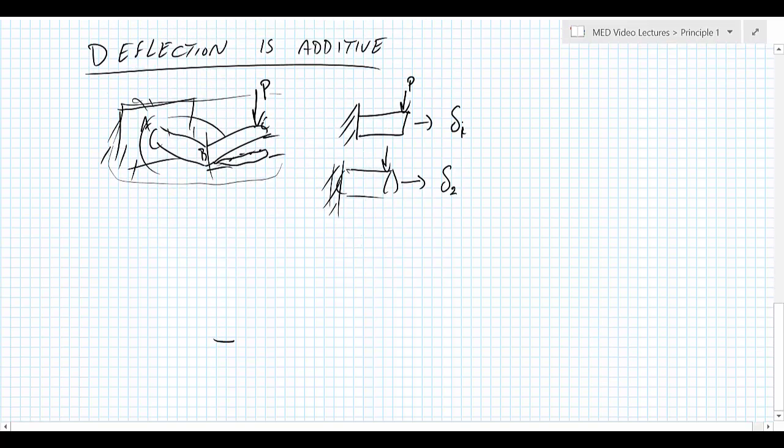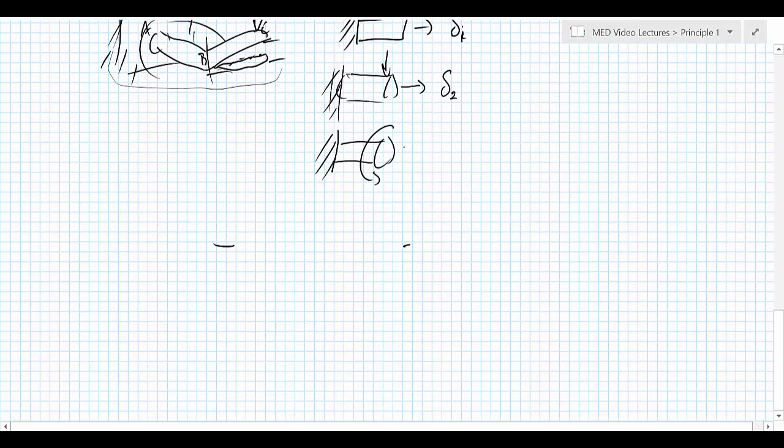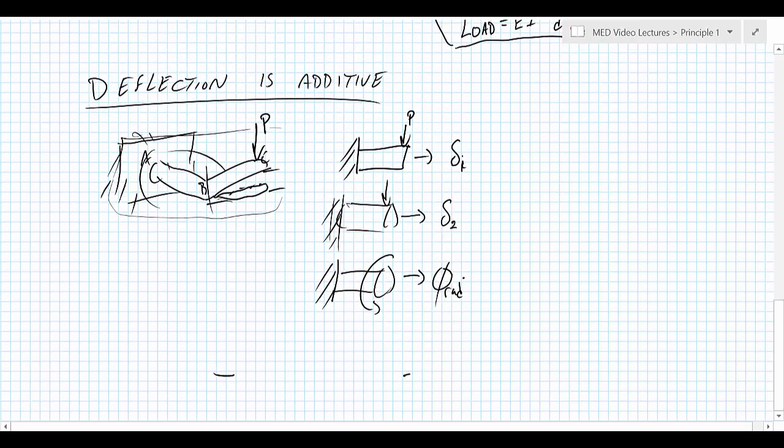And because the load is eccentric, it's also going to cause some amount of twist. I drew that backwards, it should actually go the other way. So that's going to result in some twist angle in radians. We can multiply that times the length that is between B and C and come up with how much it's going to deflect between that part. So total deflection is going to be the sum of all the little parts.